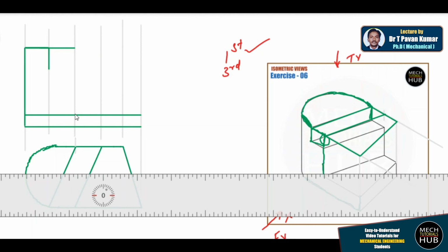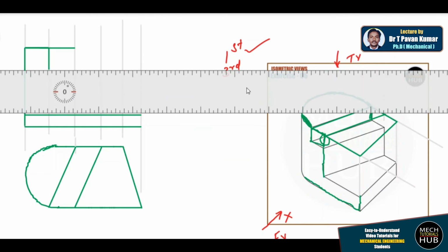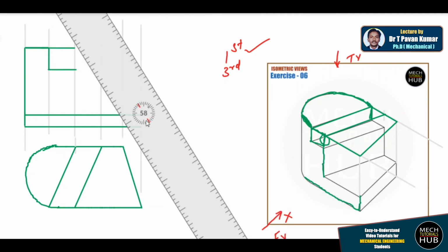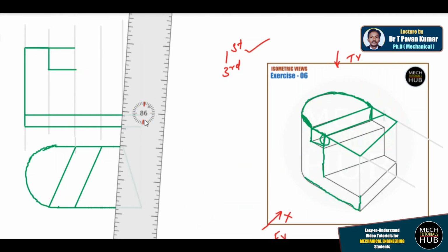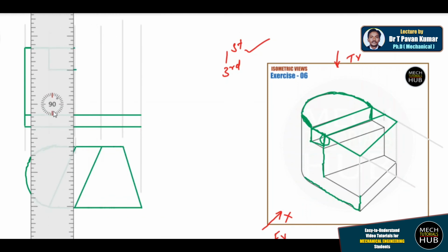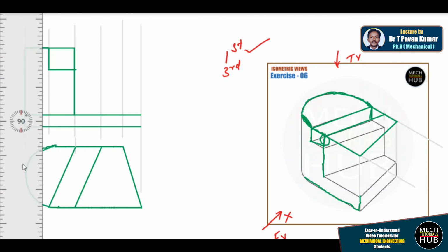Okay, that is also fine. Then again, this horizontal we need to drop. This horizontal is important. Now remember, whatever the green lines you could see, imagine that those lines are drawn with HB pencil, need to be dark, and that is the reason those are the visible lines, what we call. And now I need to drop a line till the bottom, second bottom horizontal. Till here it is fine. I'm done till this point. This line is drawn, this 10 mm bottom extension horizontal, then a vertical.